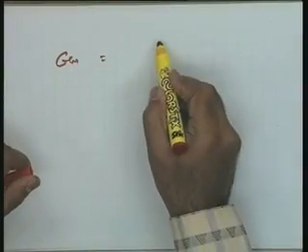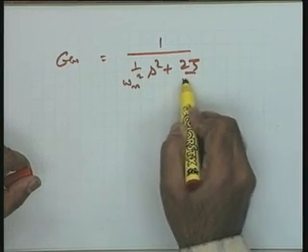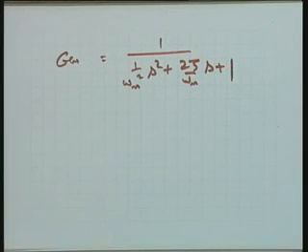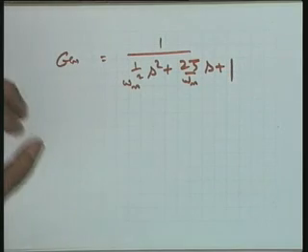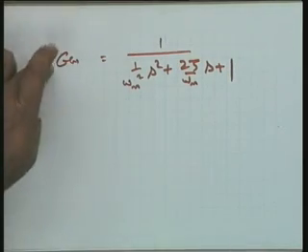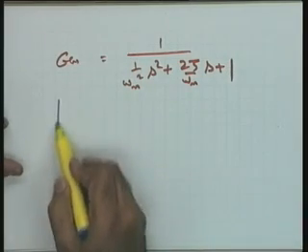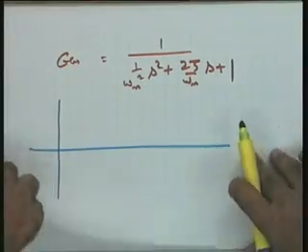Now, one more factor is there, and that factor is G(s) equal to 1 over (s squared over omega n squared plus 2 zeta s over omega n plus 1). This is one more factor. Please see, before I go to this factor, I will give you the idea of how to take up the phase margin and gain margin on the Bode plot, because even if I do not get time for this, I will tell you to study on your own, but the gain margin and phase margin idea I have to give. Please help me. Let me retain this; if I get time, I will come back to this.